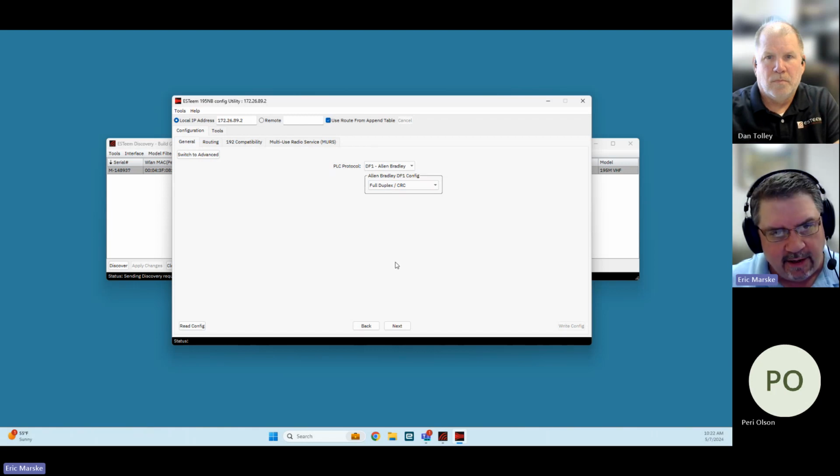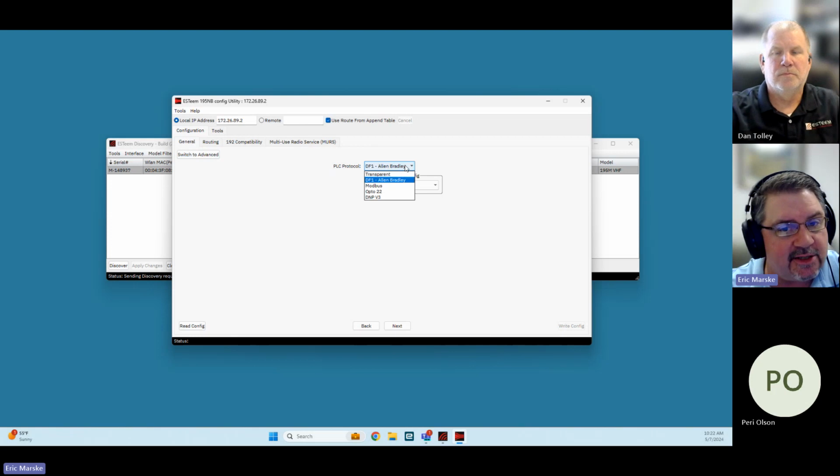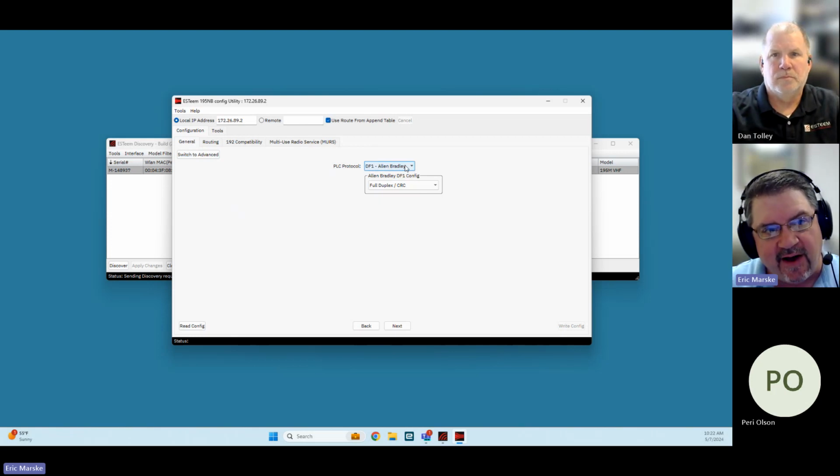And why this is important is that if we have an emulation driver specifically written for the PLC, say for the Allen Bradley DF1, Modbus, or Opto22, the radio will automatically adjust, will find the destination address and make that our own destination address as we send it out to those remote sites.